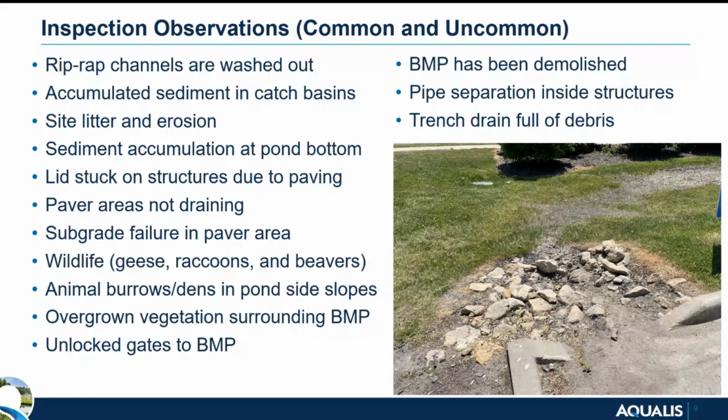So the first one, riprap channels are washed out. So this is at a curb cut at a parking lot, and you can see the accumulation of sediment and the runoff of dirty water. And so this riprap channel has seen better days. It's functioned well, but we need it to be refreshed. So that's something we'll call out in our inspection memo.